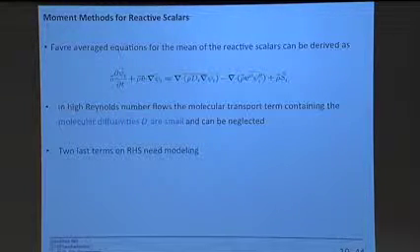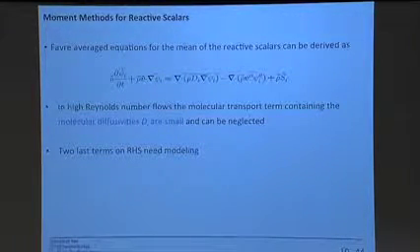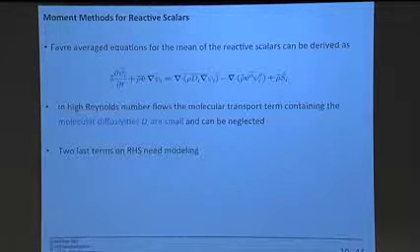Turns out, in turbulent flows, or in this Reynolds average approximation, I said this earlier, for the smallest possible Reynolds number where you get a turbulent flow, the turbulent transport is at least 100 times faster than the molecular transport, okay?